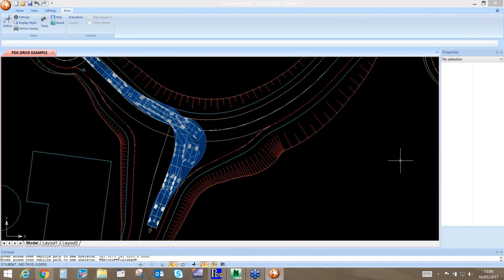So you are able to put flow controls on manholes. If you wanted to have those offline, you could also have them offline, but as an actual pipe rather than a dummy pipe. The reason you get the instability is because of the diameter to length being lower than a 10:1 ratio.